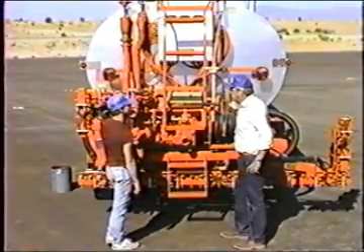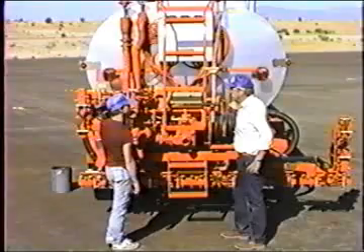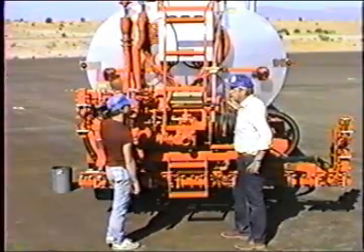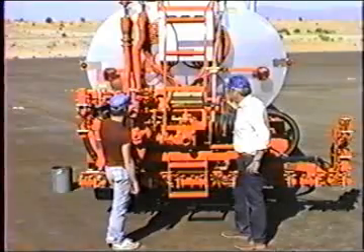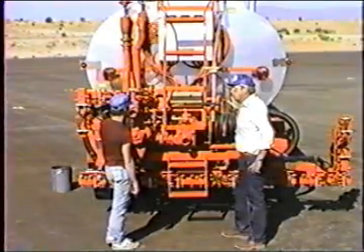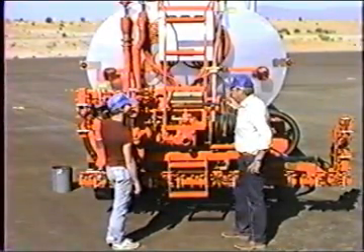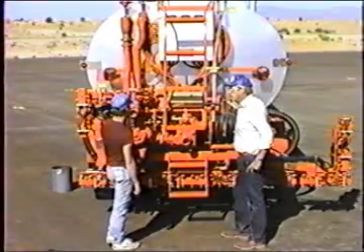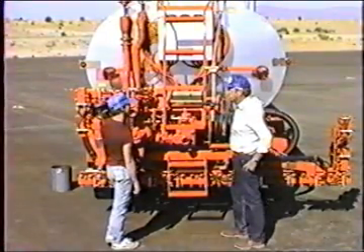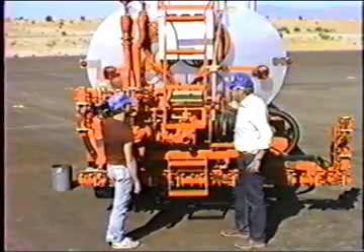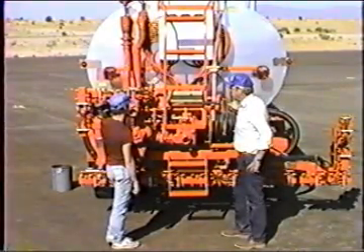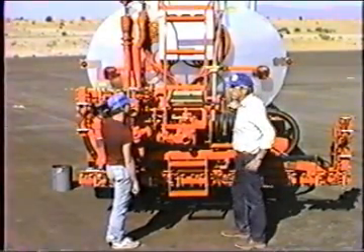Some asphalt supply tank farms that you work out of are very clean. You may work out of one plant where you can go all season and never have to clean the screen. Other plants you work out of, you might have to clean the screens twice on every load. It totally depends on the condition of the tank farm, on the condition of the transport tankers that are bringing the material, and finally the condition of this tank.